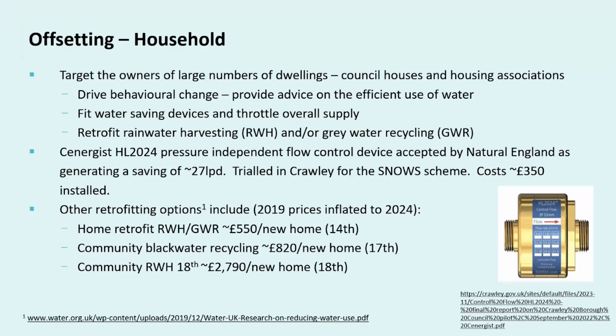Fitting a flow control device, such as the Synergist HL2024 pressure independent flow control device, pictured here, onto the cold water feed can provide a PCC reduction of at least 27 litres per person per day from existing homes. So based on our example house, the reduced PCC of 56.3 after water efficient fixtures and fittings and rainwater harvesting could be offset by fitting just 2 Synergist devices, or 1 Synergist device to 2 properties, assuming that occupancy rates are the same.